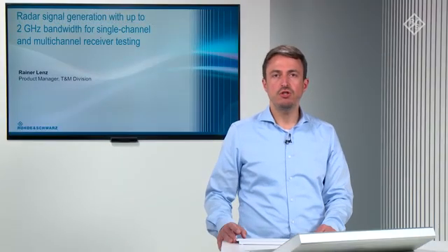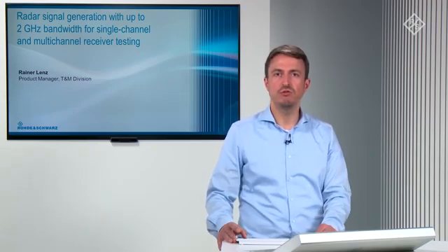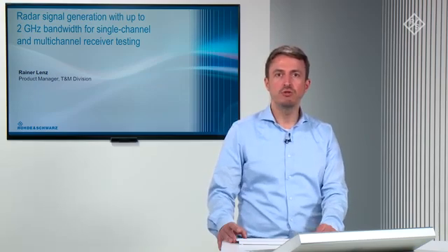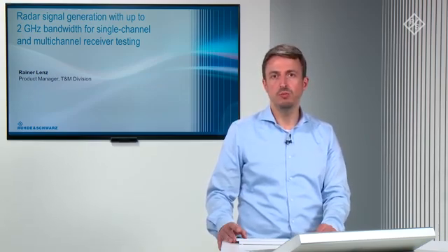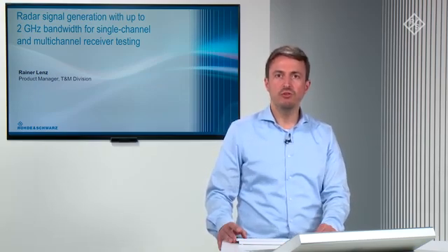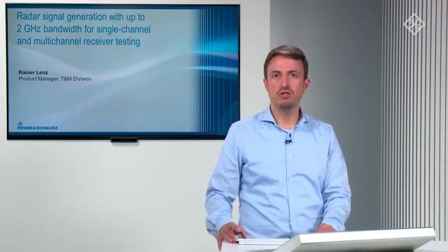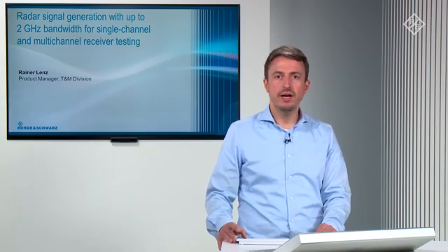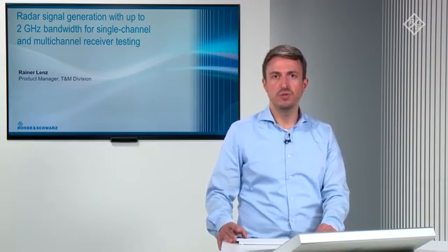So up to now, we have only looked at antenna patterns and antenna scans. But antenna polarization is also an important point to notice. Antenna polarization can have an important effect on the received power level of the receiver. If the transmitting antenna polarization is not matching the polarization of the receiving antenna, there might be a considerable power loss in the simulation. Therefore, the pulse sequencer software also supports the use of antenna polarization for both the transmitter antennas and also the receiver antennas. How this looks, I will show you in the following slide.